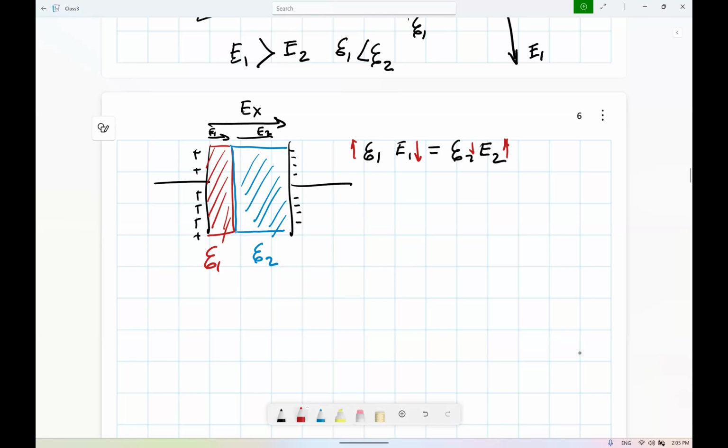Permittivity is the property of the material. What it is telling you is how it forms these dipoles, right? Plus, minus, are the dipoles. But the permittivity is the property of the material to form dipoles. It doesn't relate to the thickness. You compensate the property with the thickness, to soften the field. At that point, the field is larger, right? Yeah. So if you have a larger field, you need more material to prevent it from breaking.